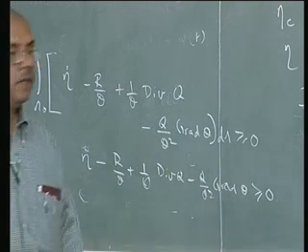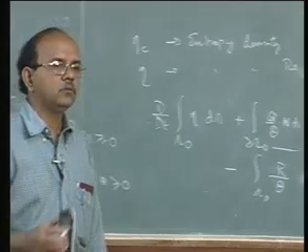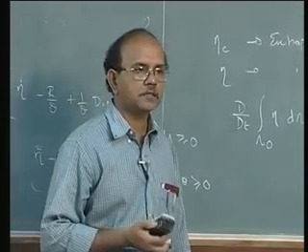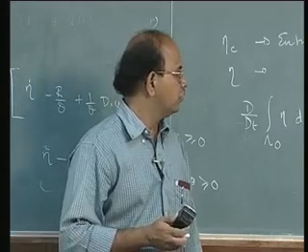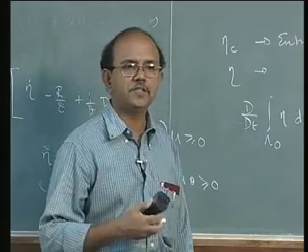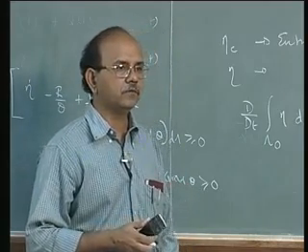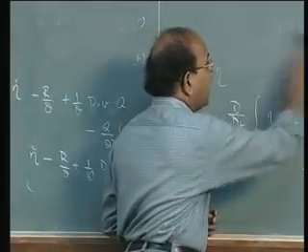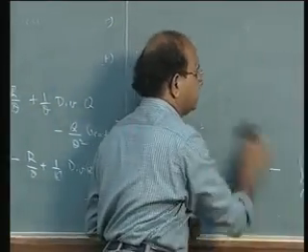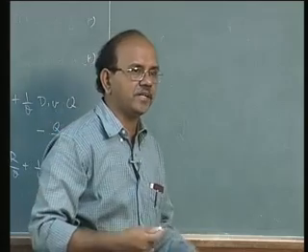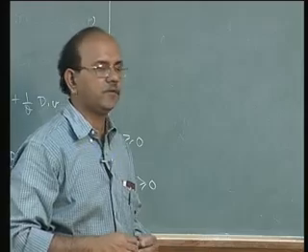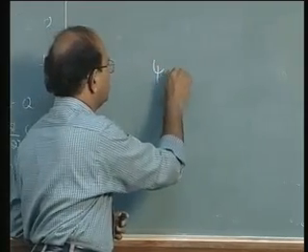Okay. Now, we had in the last course, maybe even the beginning of this course, introduced a term called strain energy density function. We call this psi. Under the thermodynamic setting, when we have entropy and temperatures and so on, the strain energy density function is replaced by what is called the Helmholtz free energy.